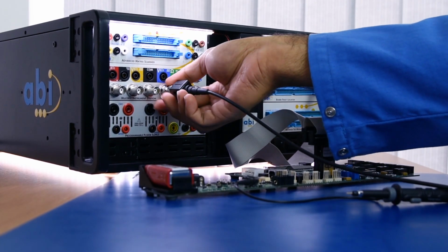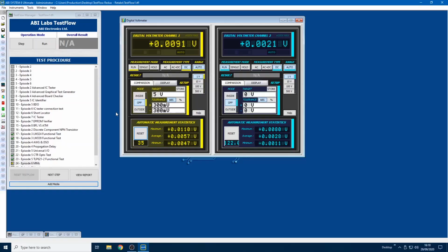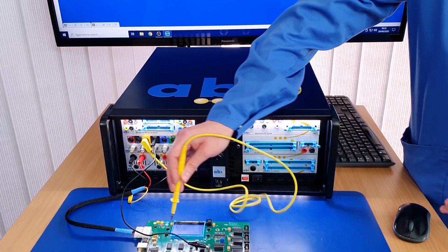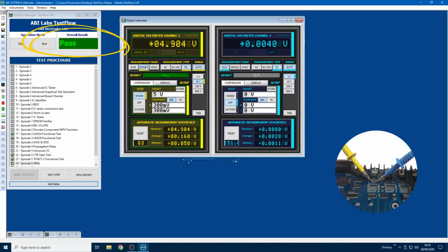Yes, of course. So it works like all our other meters. They've all got built-in comparison. So in this case, we've set a target of 5 volts, which I'm expecting from the board. As it's running already, I'll take my tolerance inside my target. Of course, I'm measuring 0 volts at the moment, so I'm going to get a fail, but not until I actually measure the point I'm looking for will I get a pass. And I'll take a single measurement of that so I can release the probe.